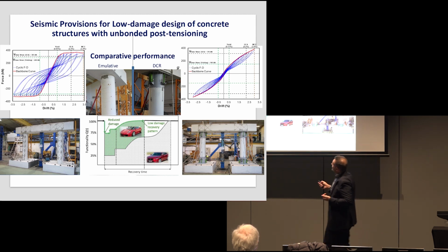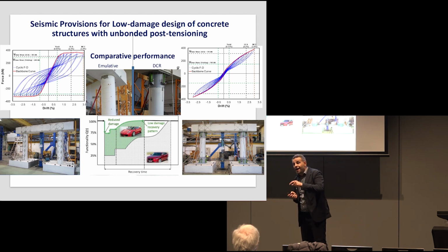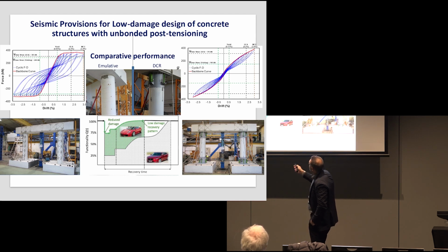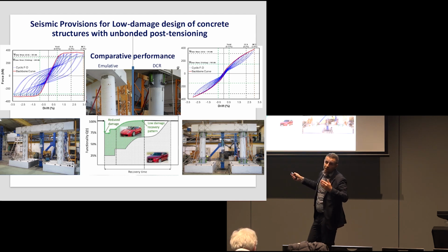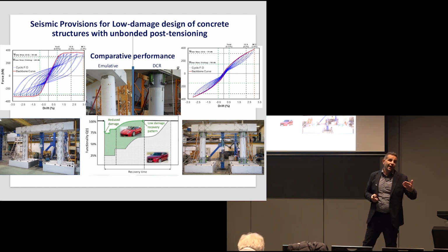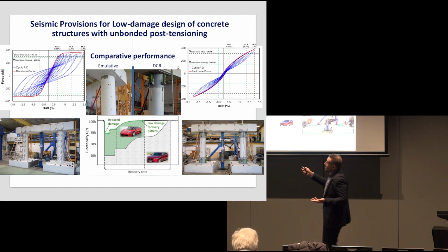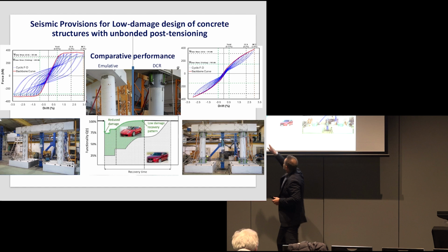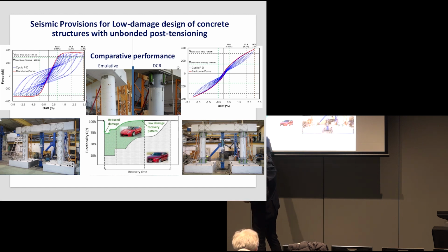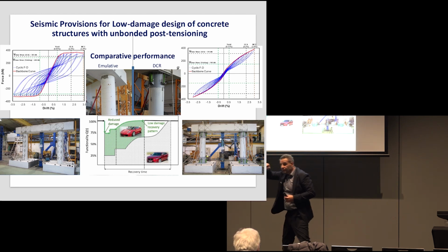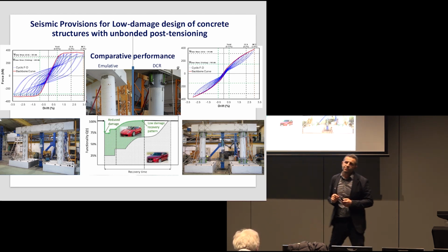The other thing is that if we have monitoring on the devices, we can know exactly what the strain demand is, and if the earthquake level is not producing high strains, we can simply say we are at 100%. But you can see then with the red, the Ferrari, the recovery time is far shorter, the drop is far lower, and therefore the area, the R factor, the resilience factor, gets better.